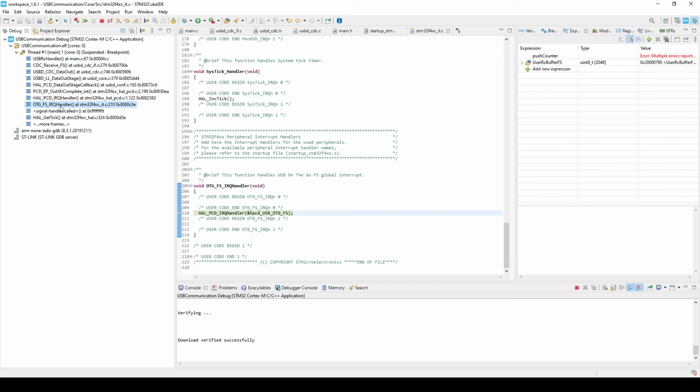So the microcontroller stopped running that part of the code and jumped to the interrupt handler to handle the interrupt that happened. In the datasheet of the STM32, it clearly says you should not stop the interrupt from running. If you do, you will encounter a situation called a hard fault handler. The microcontroller will stop and you need to restart it, because the interrupt shouldn't be stopped from running.